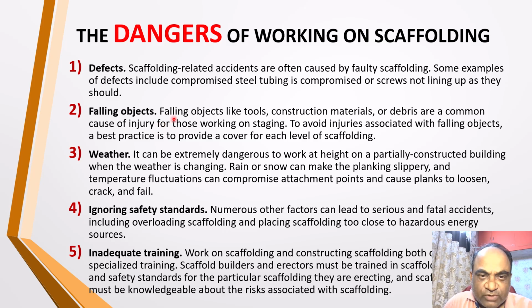Falling objects. Falling objects like tools, construction materials, or debris are a common cause of injury for those working on a staging. To avoid injuries associated with falling objects, a best practice is to provide a cover for each level of the scaffolding.